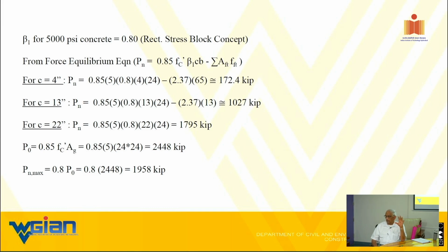Unless we come up with a better definition of how the compression GFRP controls, otherwise we will never be able to make a doubly reinforced beam, and what max percentage you are talking about. All these cannot be well defined without analysis of the compression side. Exactly.